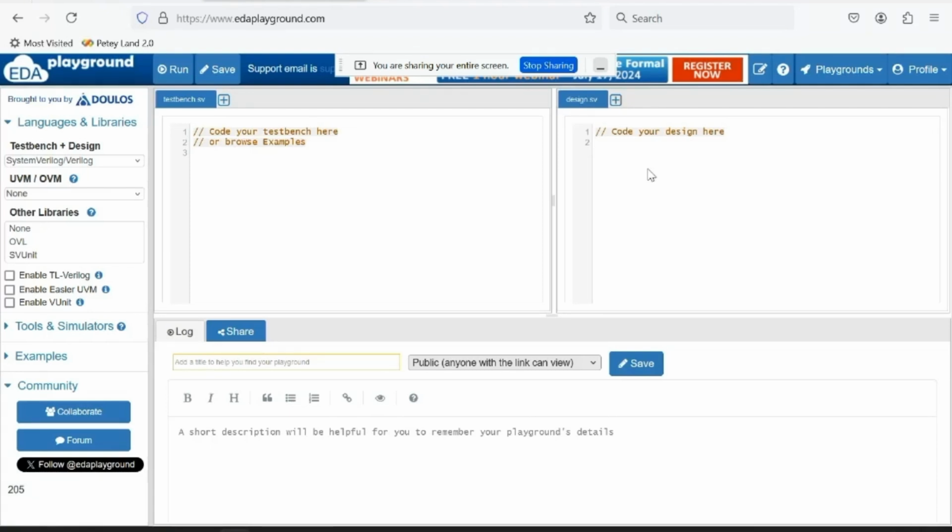Now I'm going to show you how to write the Verilog code for the 1 cross 2 demultiplexer. First, let's start with module followed by some name. Input S, another input I, and as per our hardware circuit, Y0 and Y1 are the outputs.